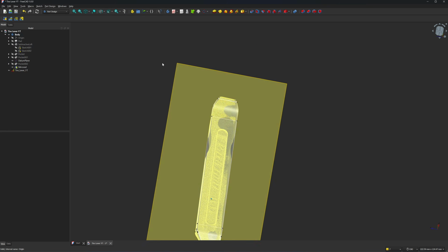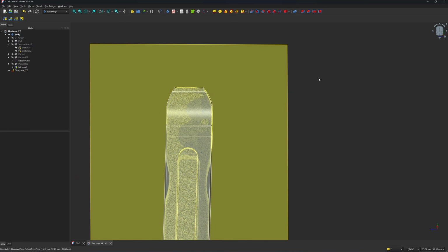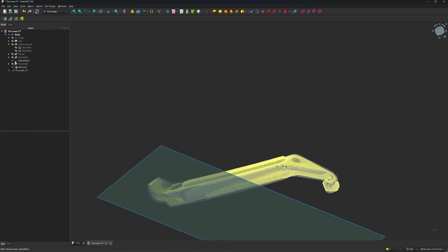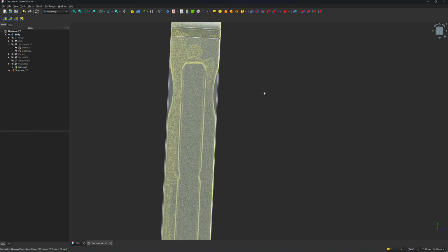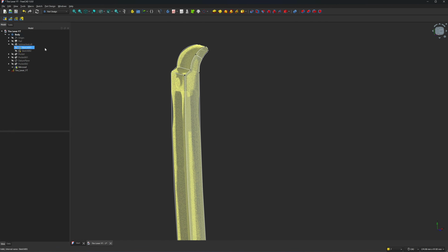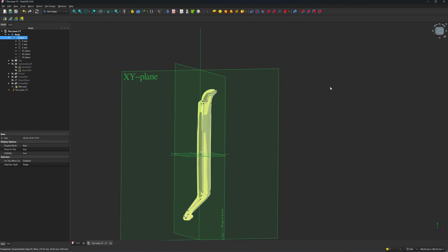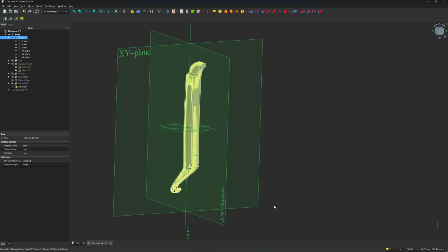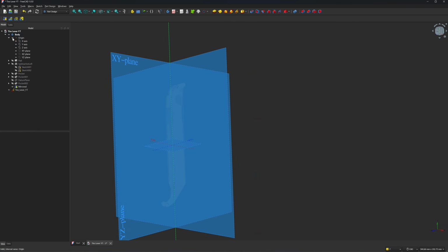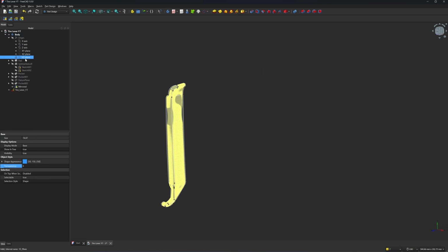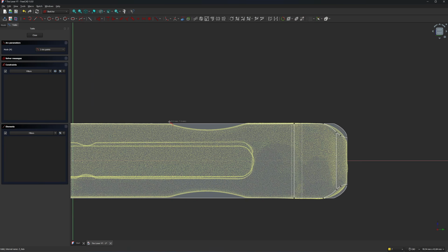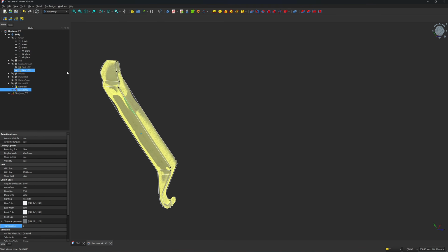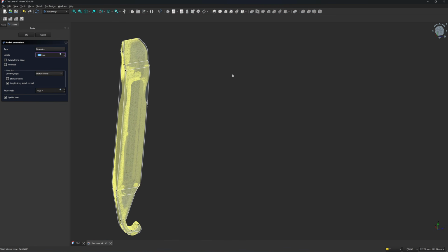Let me try. Okay, so you can draw just one half of the sketch, extrude cut, and then mirror the feature. So that's nice. Okay, so they have a contour cut here for gripping with the thumb. So let me try. Which plane is that? Yeah, I think I can draw it on the YZ plane. Cut it. Don't need to create a plane. YZ plane. Click on sketch. Okay, I'm going to draw an arc to cut this. Close. Alright, and then I'm going to cut this using a pocket command.